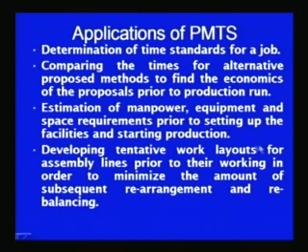If the layout has been arranged in such a way that this will take minimum time for completing a given task or for achieving the desired level of production, then that would be beneficial. So, in the initial stages, if we are planning to have one type of layout, then how much time it will take to complete the production, and if we are having another type of layout, then how much time it will take. So, that can be easily estimated with the PMTS method, and thereby it helps in developing the tentative work layouts.